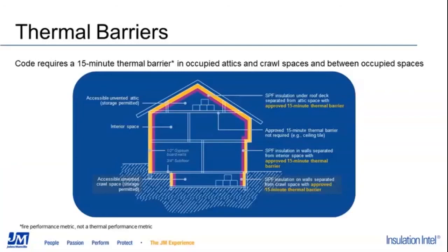No problem. When it comes to the 15-minute thermal barrier, the Canadian code says that any spray foam that has a heat-emitting source in the room has to have a 15-minute fire barrier. Typically, that's going to be drywall for the most part, but if you're not planning on drywalling the room, there are fireproofing paints, thermal barrier paints, that you can apply to everything, and that's what this is probably referring to in your attic, because you're probably not going to cover it all with your drywall. You're going to put on this thermal barrier paint to cover it up to give it that 15-minute fire barrier so that it meets code.